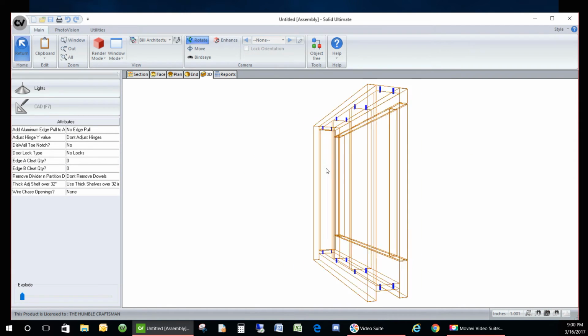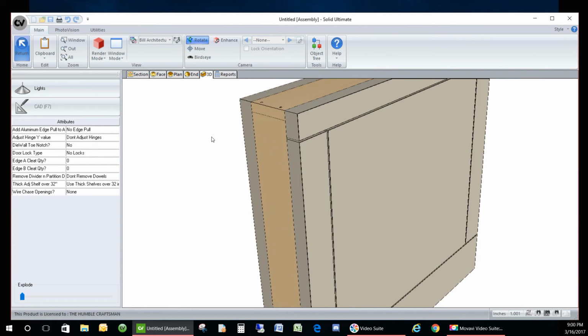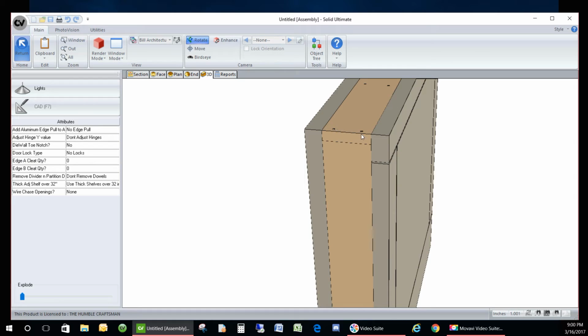So some companies use about 1.25 inches of material past the plates. What I've seen a lot, and why these by default are called out at 1.25 inches, is because usually they'll have 2 layers of 3/8 or a single layer of 3/4 that wraps around the shape, and then they'll have a layer of 1/2 inch, which is their cleating stock that they use on the surface to anchor the exterior panel with.